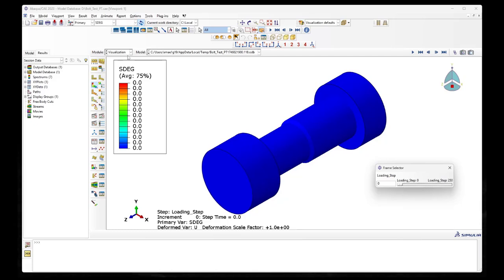Also, there are other damage criteria present that you can define. We just covered the ductile damage definition. There are also the shear damage criteria and the Johnson-Cook criteria, so you can define those as well. You can define multiple criteria for the same model, depending, of course, on how general and what kind of forces are being applied in your simulations. You can read more about those in the Abaqus manual, but the same basics that we discussed today apply to those as well.